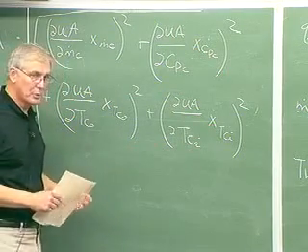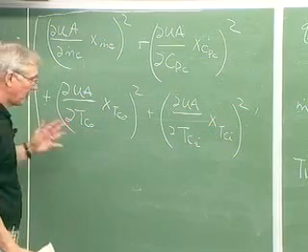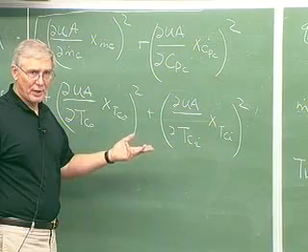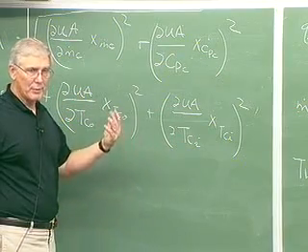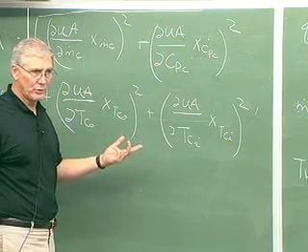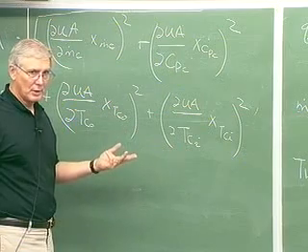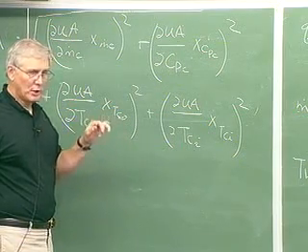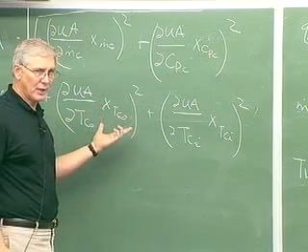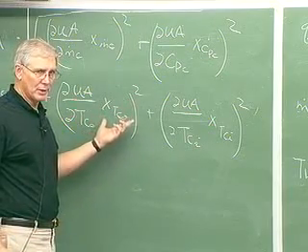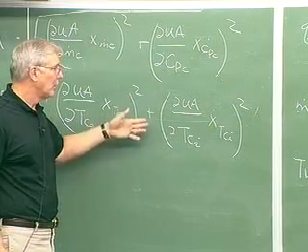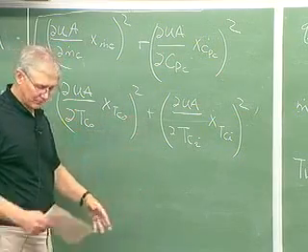Okay, my suggestion would be to write the term for UA out in its entirety using MATLAB. Then with MATLAB, you can tell it to take the partial derivative symbolically with respect to each term. Then you can copy and paste and put that into Excel. Then you'll have the formula in Excel for each partial derivative, and you can use your spreadsheet to find the uncertainty for each condition.